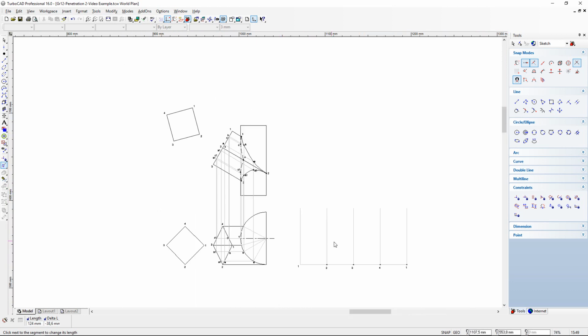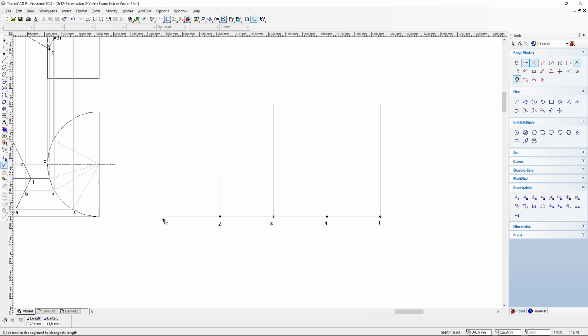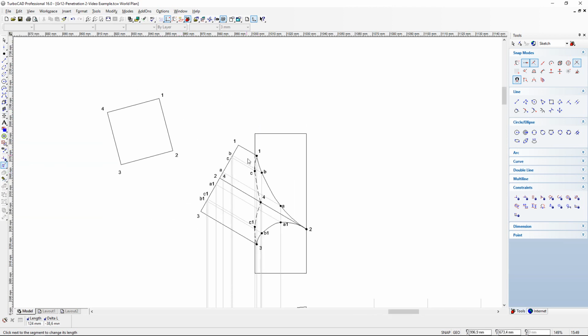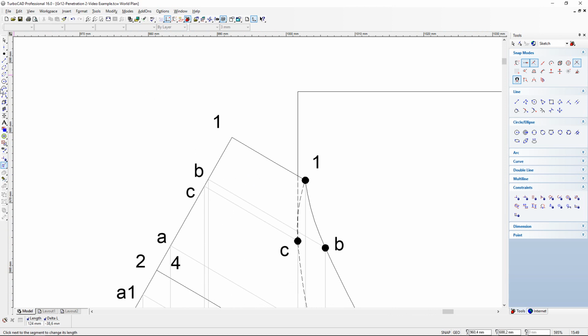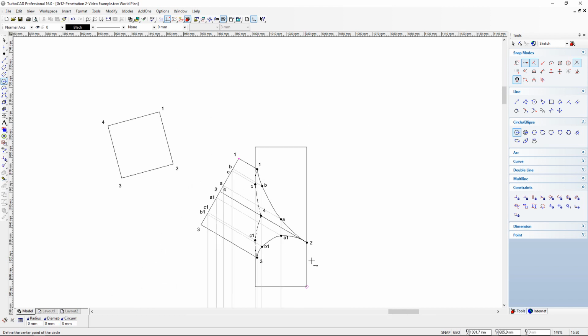But when we unfold it, obviously, we have all the numbers spread out evenly, as we see here, each with the same segment distance. So what I want to do is determine the height now of number 1, and I'm going to measure from the base of number 1 to the height where number 1 will be cut off and where the interpenetration happens with the half cylinder. So for number 1, we have now 12.3 as a distance for the height.